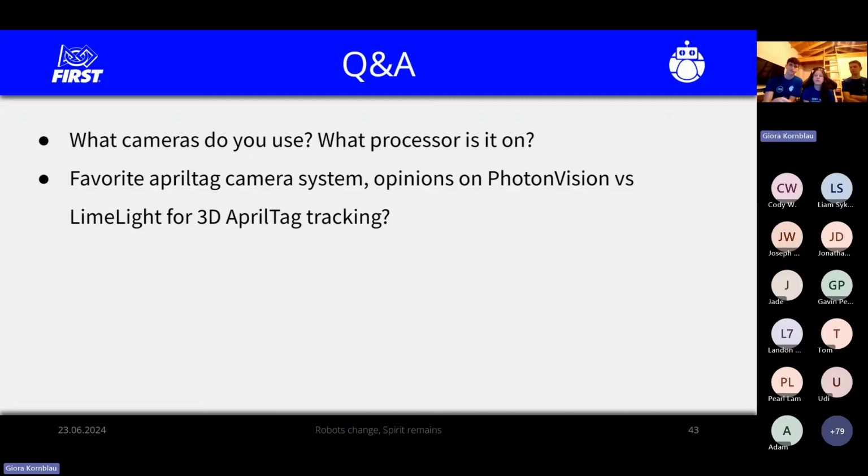Someone also asked us why on Einstein we put the wheels at zero. It was because we had some issues in the connections of the encoders, so we wanted to make sure that we get the right movement, and that we're not drifting in some weird way caused by one module that is not aligned with the others.